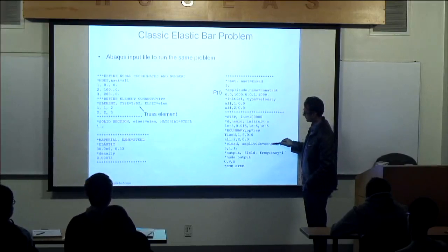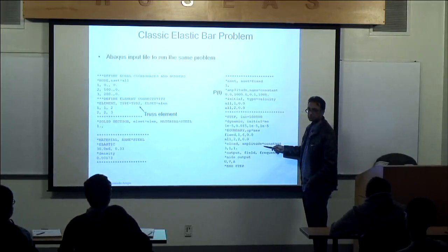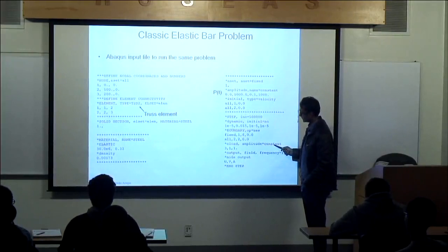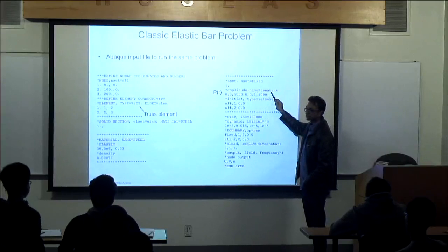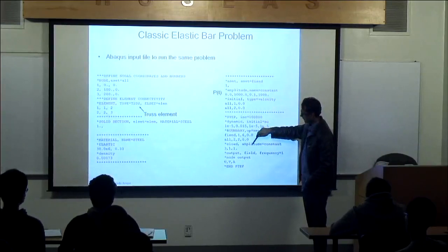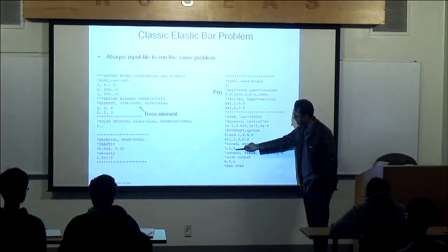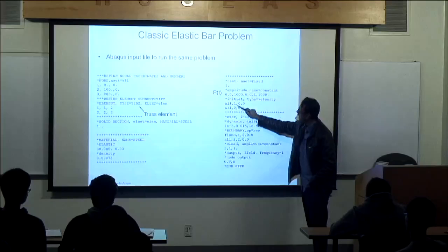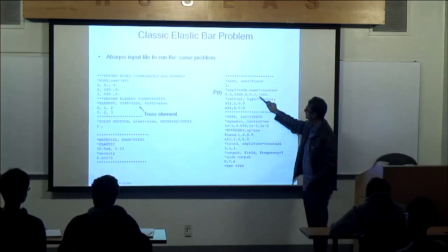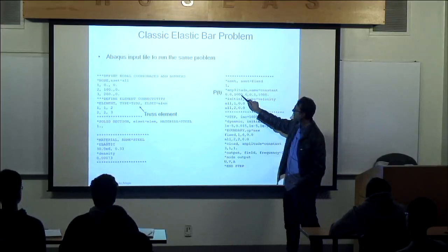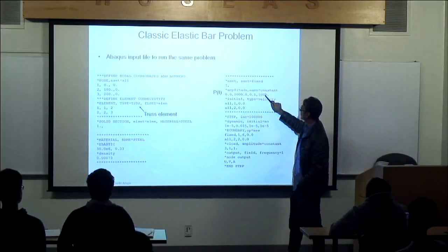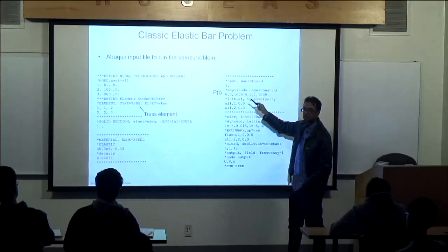You make up this name. You can call it your name. You know, amplitude, name equals Chris. I can do that. Then I'll have 3, 1, 1.0. And this 1.0 will get multiplied by this 1,000. And it's going to use this amplitude. This is basically saying 1,000 pounds at time equals 0, 1,000 pounds at 0.1 seconds. So it's keeping it constant.